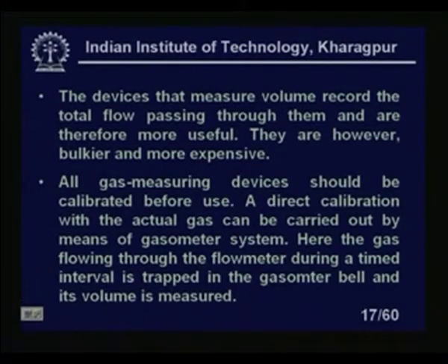Rotameter is a very simple device, as you know, a very indicating sort of instrument. We have studied this in detail in flow meters, but there are other devices, like turbine flow meters or any other gas flow meters, and an orifice meter also, though that is obviously bulkier. All gas measuring devices should be calibrated before use, because you are measuring the volume, so how much collection we are taking should be calibrated beforehand.